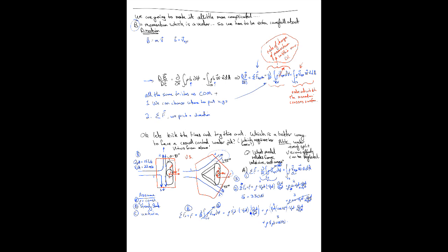And we multiply by the area again, which is q jet divided by v jet squared. And remember, the whole reason we can assume that our fluid leaves at the same velocity is because we're assuming it's inviscid. So if we don't have any viscous effects, there's nothing to slow it down, right? It's just going to keep its same momentum. Any kind of pressure will just change its direction. It will not change its velocity.